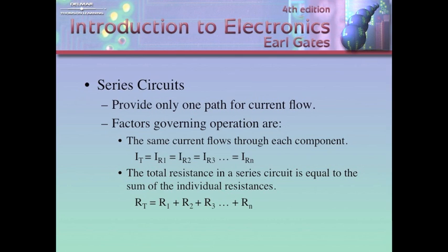That's a very important concept as a technician when you're troubleshooting a piece of equipment. If you know it's a series circuit and you know how much current is going into that, there's only one way in and one way out. If you put 10 amps in and you're only getting 8 amps out, 2 amps must be going somewhere. That's your problem. That's what you have to find, where that current is going. So this is a very, very important troubleshooting tool.